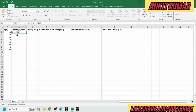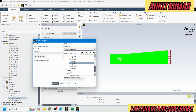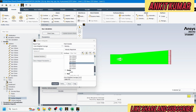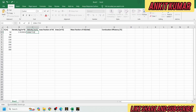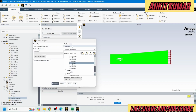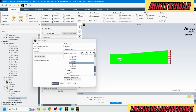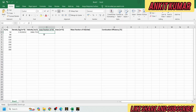Next, I require velocity at 50 mm. So I will choose from here the field variable velocity magnitude, and click on compute. It will give the velocity value. Now I will copy this one, Control C, and paste this velocity here. Okay, now mass fraction of hydrogen. In order to calculate it, in ANSYS Fluent, from field variable choose species, mass fraction of hydrogen, at line 50 mm. Click on compute. It will give the mass fraction of hydrogen. Again we can select this one, press Ctrl C, and paste this value in the Excel sheet.